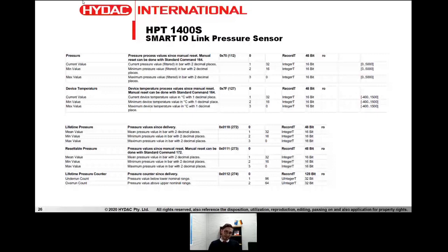As I explained earlier, we do temperature compensation on the sensor for linearization. To do that, we need a temperature sensor, and that temperature sensor sits inside the cell on the electronics part. So you can actually measure the temperature and give a good representation of what the fluid is, but I wouldn't use it as a temperature controlling device. You can use it to see if the sensor is going above temperature itself, and you can record that value, and maybe you can calibrate the temperature value of the sensor to your process, and you may actually be able to use it as something to control your process.